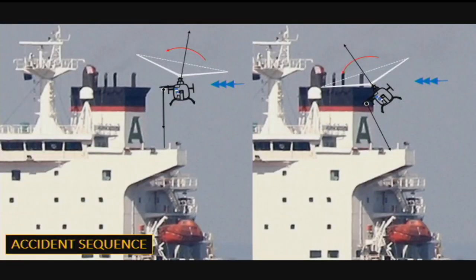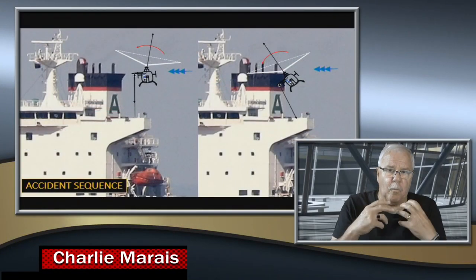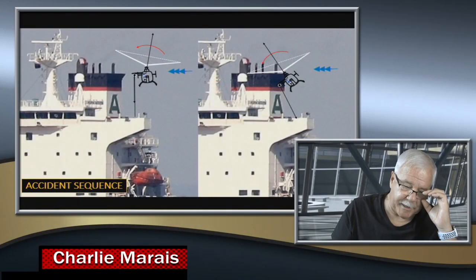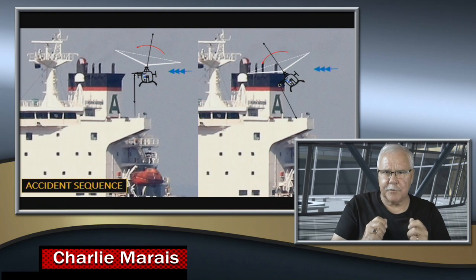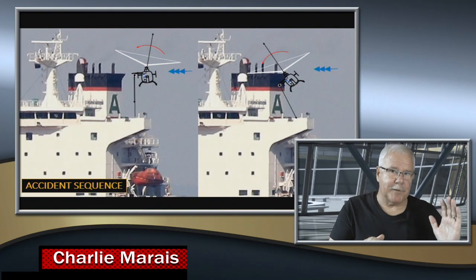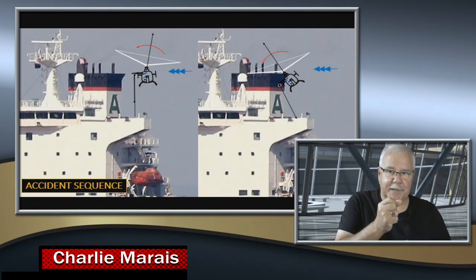But let's have a look here. It's maybe better to say that once you look at the physical aircraft and the evidence that is in front of us, let's consider it a little bit. Everything had to do with the control of the helicopter. Now remember, the first thing that we said is that the wind was coming from the left-hand side, and the cyclic stick, and that's the stick in the center, had then to move to compensate for that.